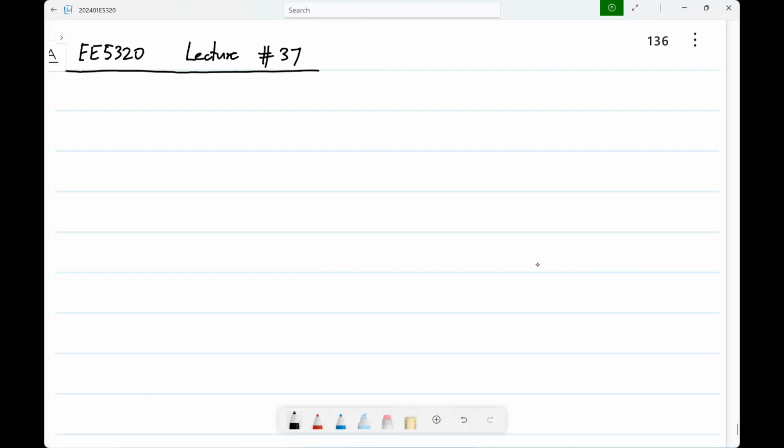Now, to analyze these, we have differential and common mode half circuits. The common mode half circuit of the common mode feedback is another negative feedback loop, so knowing what you know about negative feedback circuits, you can analyze them. Many of the common mode feedback circuits that we have seen correspond to either one amplifier or two amplifier stages in feedback. The same rules apply for the loop gain, for the step response to be well behaved, and so on. In simulation, you will have to check the behavior with both differential excitation and common mode excitation.